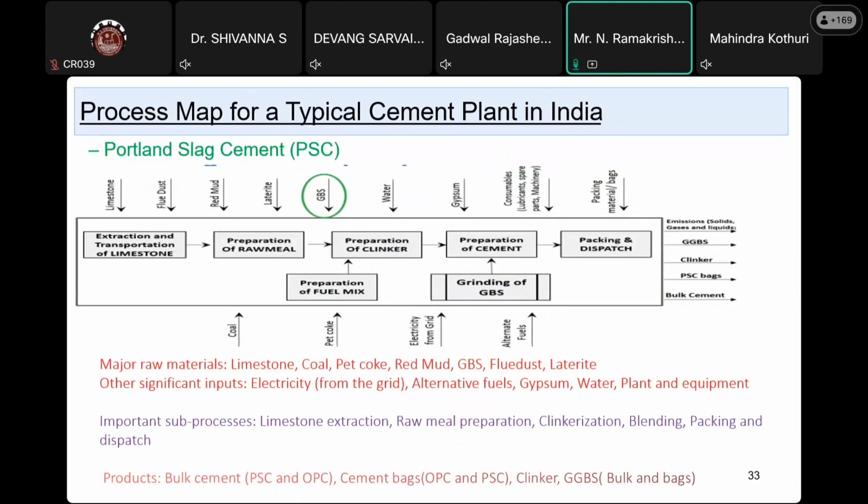So the selection of the material, as I told you, GGBS properties and fineness is also very, very important. So of course, you know 33 grade, 43 grade, 53 grade, what is the fineness and what is the GGBS fineness, fly ash fineness, all will play an important role. So rate of cooling as well as fineness are also very, very important. So instead of fly ash, you are using here GGBS.